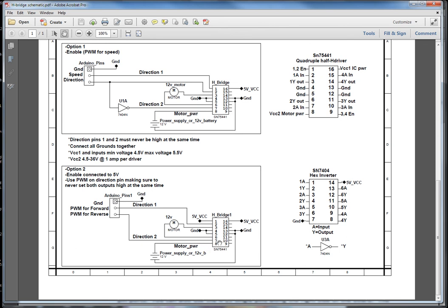Okay, and while I have this open, I just want to mention too, the two input pins are 2 and 7. That's to turn on 3 and 6 to the motor. Those are the outputs. So we want to make sure that these pins 2 and 7 don't float high, because then that could possibly turn on the current at 6 and 3.